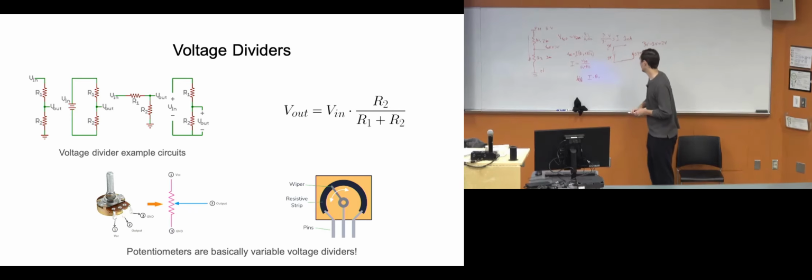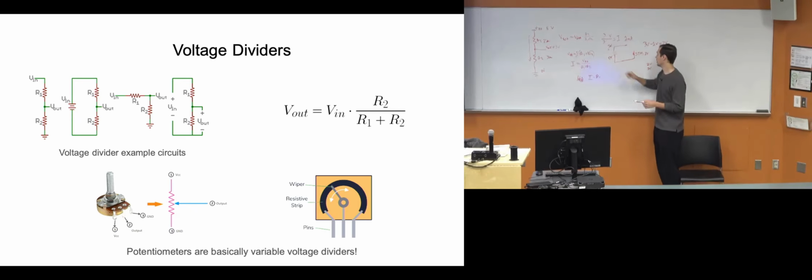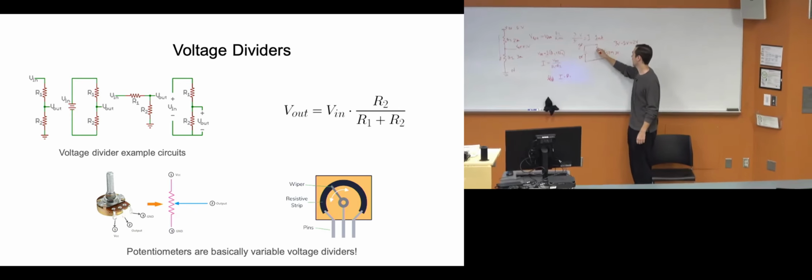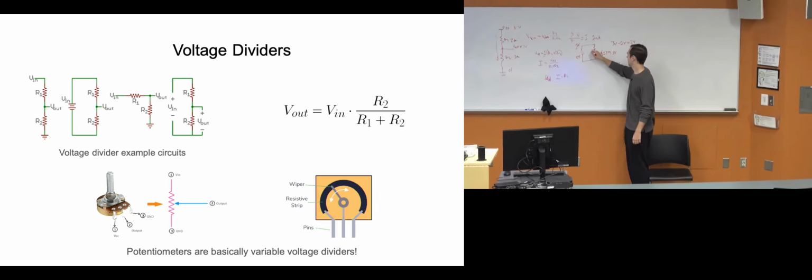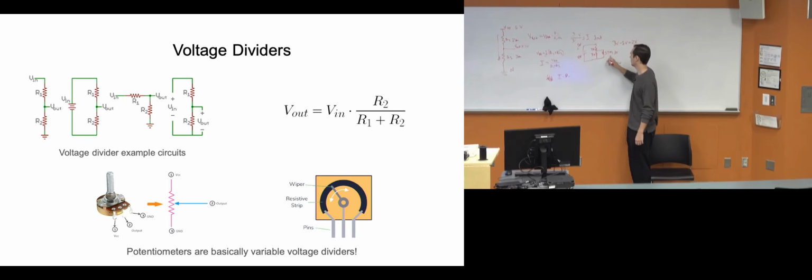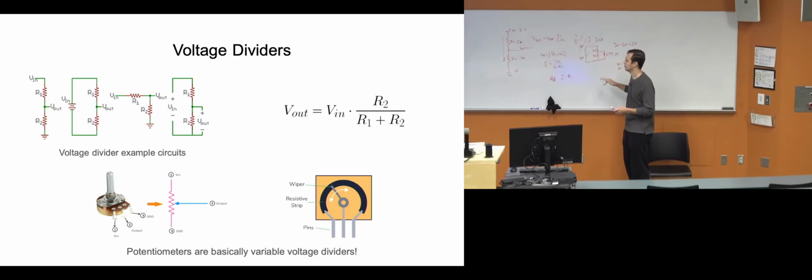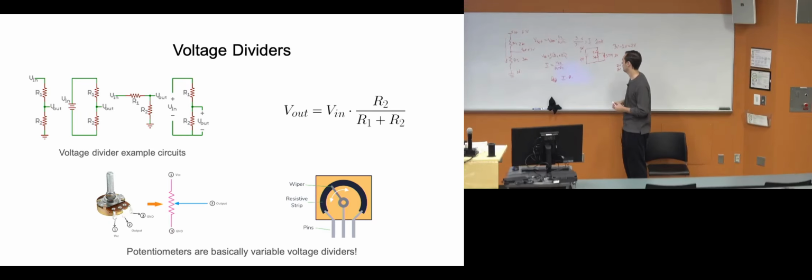OK. So yeah, you can use these just to find a ratio to drop that down. So if we had the 2K here, the 3K here, and we took this voltage, put it on, we'd have 3 volts here, and we wouldn't break our processor, right? In reality, you'd probably use a linear regulator or a buck for this to drop the voltage, but this is just for principle.